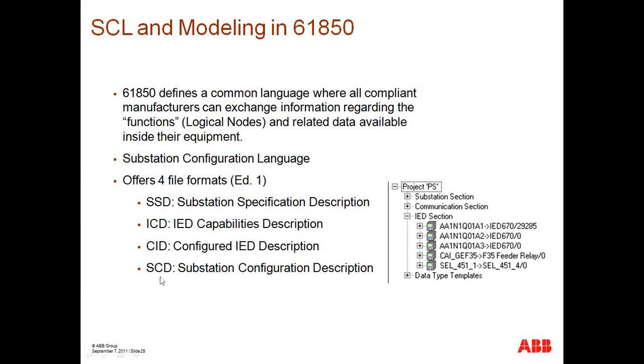And then ultimately, the one that's very important, you have an SCD, which is a substation configuration description, which is essentially a file that contains the one-line diagram of the substation, the IEDs that are part of that substation, the association of those IEDs and their respective functions to the different bays and voltage levels within the substation, and then any type of connections that exist between IEDs.